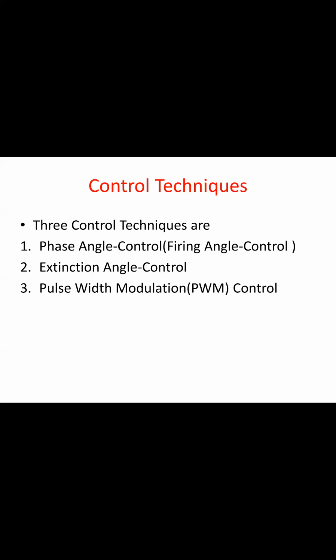In this way, you just remember that the first quadrant means diodes as well as SCRs will be there. The second quadrant and the other two quadrants mean SCRs will be there. Here the SCRs are thyristors. They permit the flow of power from the AC system to the DC system, and also from the DC system to the AC system. The flow of power from the DC system to the AC system we call the inverting mode. That's why we get two quadrants for an SCR, and if I use two SCRs, I will get four quadrants.